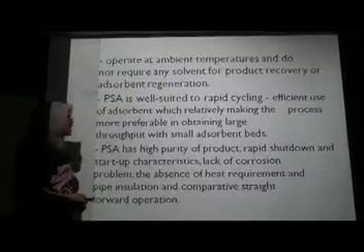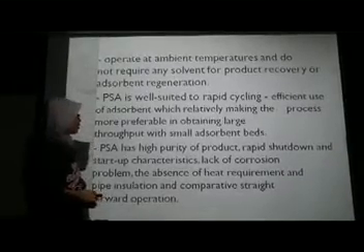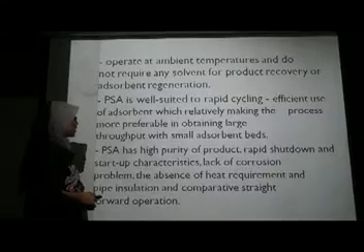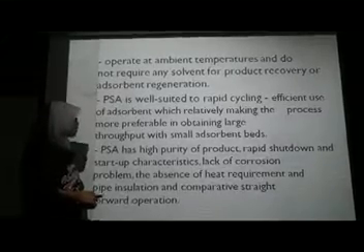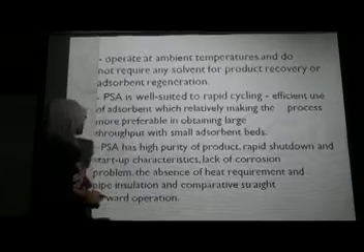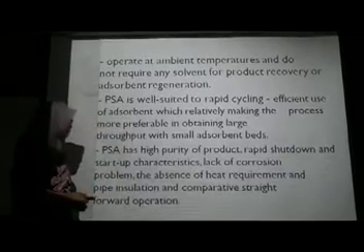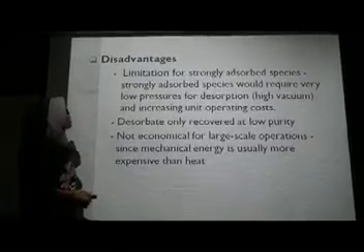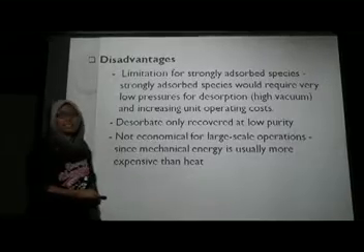Besides, PSA has high purity of product, rapid shutdown and startup characteristics, lack of corrosion problems, the absence of heat requirement and pipe insulation, and comparatively straightforward operation. Here are the advantages of PSA system.